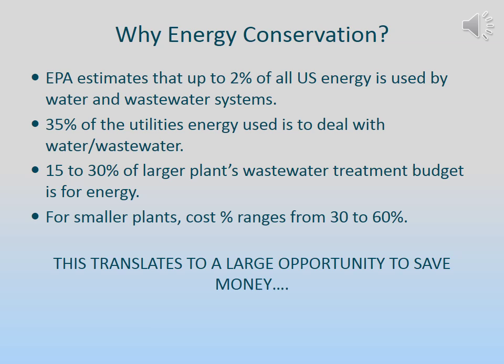There is a small water system down in a little town in Maryland which went from a regular conventional activated sludge type of process to an ENR process. When the town got their first electric bill, they were floored. The operator said to them, "Just come down and look at the generator we have. It is 5 times bigger than the one we had before." This plant is going to use a lot more power with ENR than they used with the regular process.